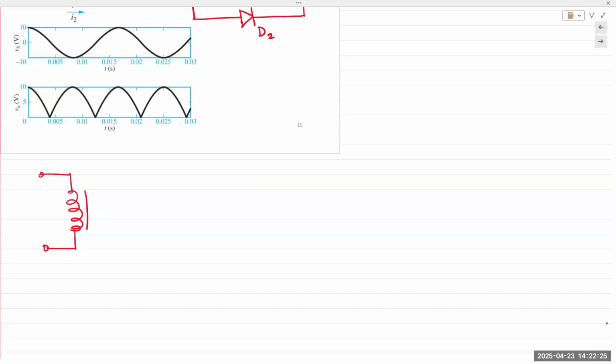Now, an inductor can be an empty air core because it's a coil, it's a winding, right? It sets up a magnetic field. If there is only air, if there is no core inside the winding, we say it's an air core winding. The magnetic field is weaker. And if you stick a ferromagnetic material inside the winding, now the core is some sort of ferromagnetic material that permits the creation of flux lines. And so the magnetic field is a little bit stronger. Operating principle of an electromagnet.